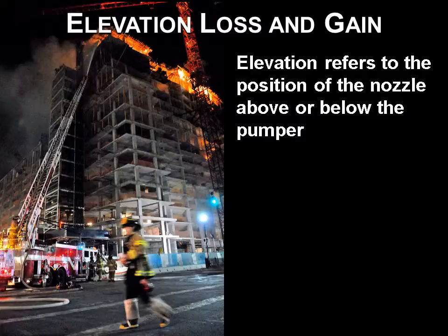Elevation loss and gain. Elevation refers to the position of the nozzle above or below the pump. Pressure loss occurs when the nozzle is above the pump. Pressure gain occurs when the nozzle is below the pump.